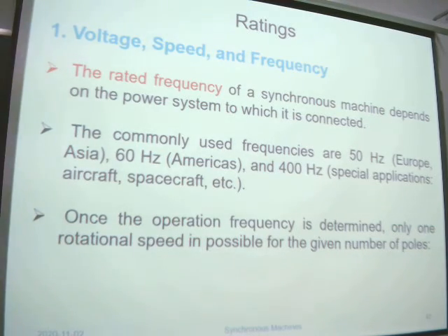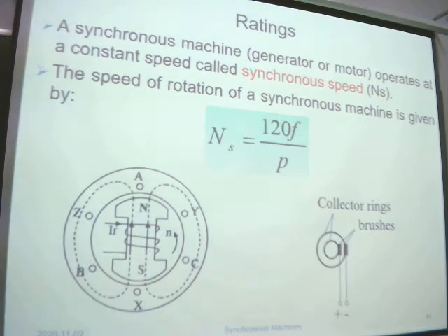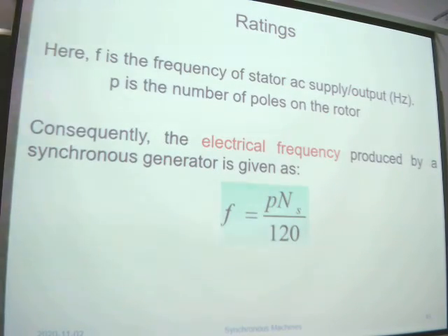And if we know the frequency, we can calculate the synchronous speed, just as we calculated in induction machines. So the speed can be calculated. If we know the speed of the rotor, we can also calculate the frequency.